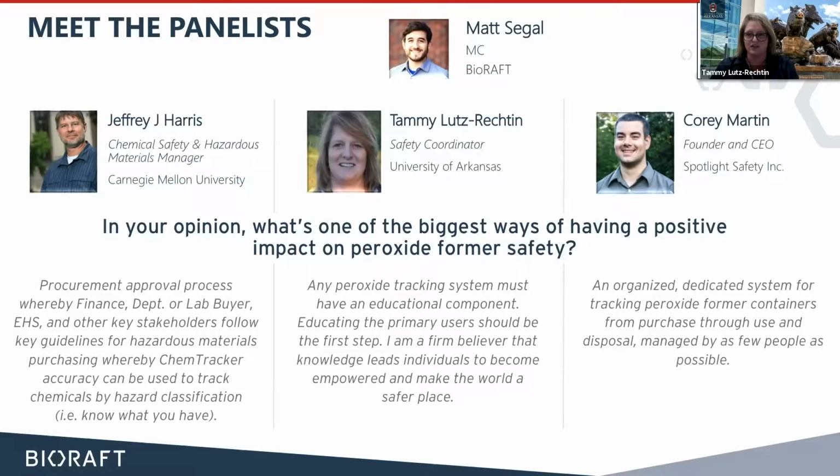But the safety data sheets actually can be really difficult. So I would check sections 2, 7, and 10, because I have found sometimes that it just says light sensitive, maybe in section 10 or under storage, or can degrade in light and form unstable peroxides that may explode. And it's not necessarily in that other hazards category within section 2.